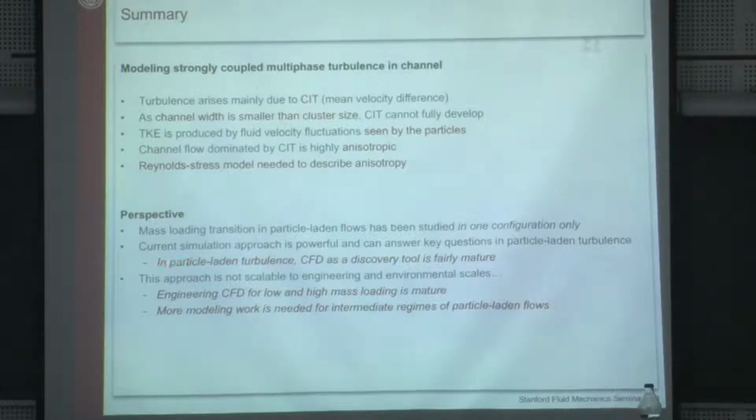I think the simulation approach I showed is very powerful, and you can take that quite a bit further. That's everything I've shown here. I think that suggests that we can certainly use CFD as a discovery tool for particle-laden flows in terms of elucidating the physics. As an engineering tool, for dilute flows, we've discussed a number of things that work well.